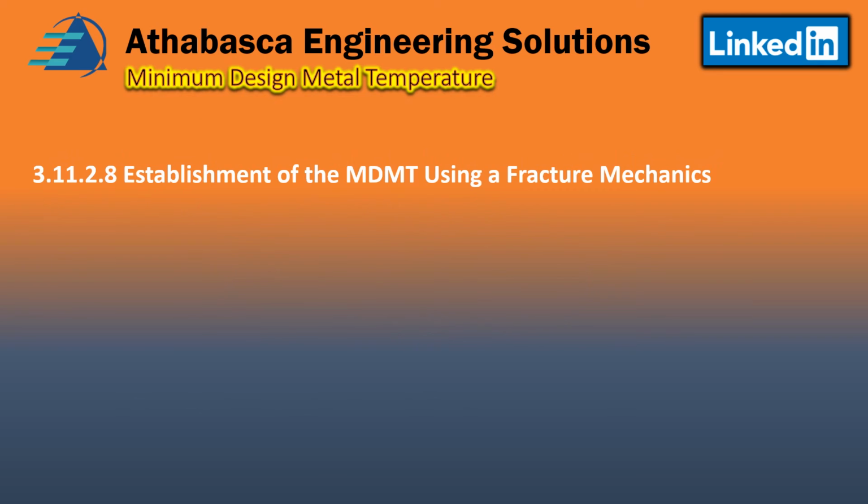So the establishment of MDMT can be used for fracture mechanics, which is unique to Division 1. If you can look up 3.11.2.8, ASME has a very good example in, I believe, one of the PTB editions.